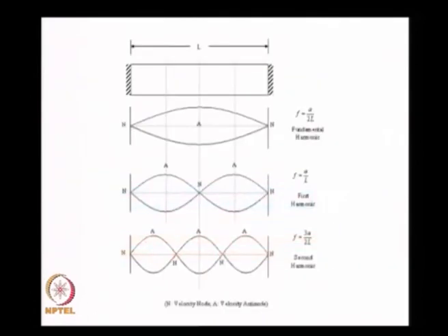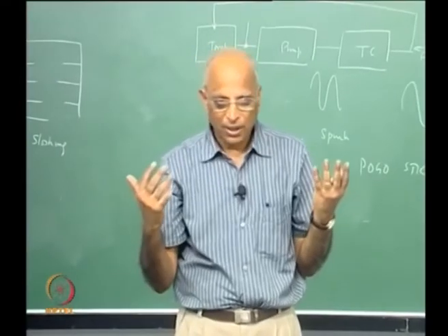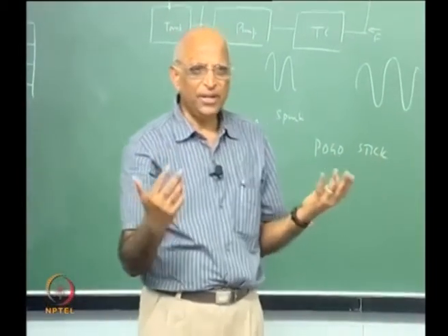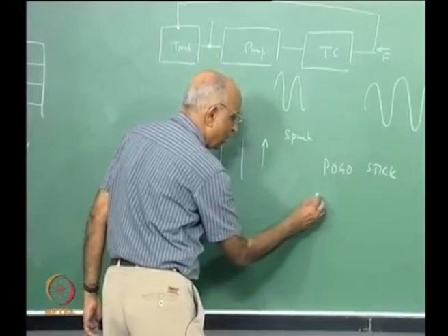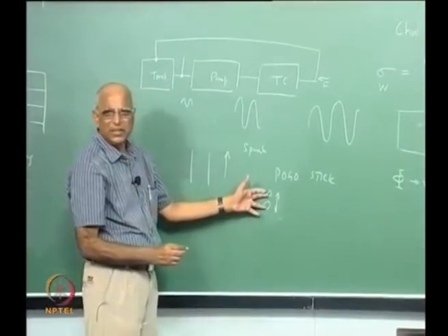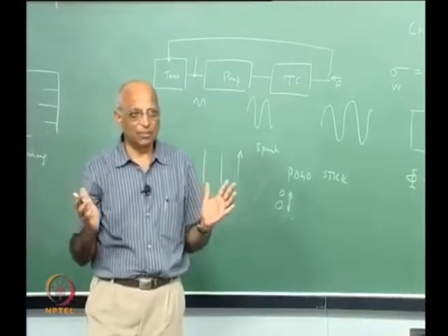Well, we will conclude by saying that a liquid propellant rocket or a solid propellant rocket is susceptible to instability, and this instability could be defined in terms of bulk mode oscillations, or wave mode oscillations, or in terms of different processes. We did not get into details of solid propellant, wherein you could have oxidizers burning up giving you a particular frequency of depletion, but these are all details, and what we have covered is the basics of combustion instability.